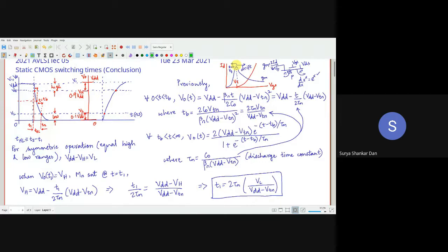What they'll do is, remember in this course also we have seen that after VT the device will be operating in the saturation region. ठीक है? So ये VT है. What is this value? VDS plus VT. This is the saturation region, correct? उसके बाद है linear. We have also shown this through our Python code also, right?